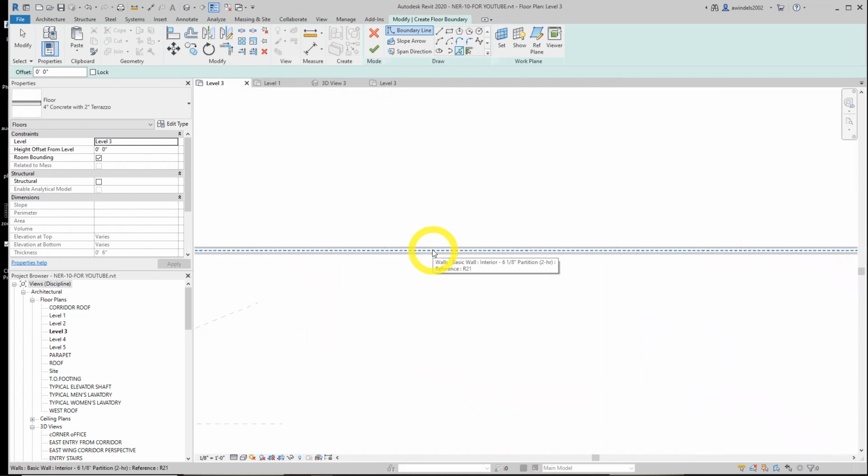Let's hover in here. And we pick the core of the wall, do 5 feet. Pick the core of the wall here. Make sure I get this right. This is maybe why my stairs weren't linking up right the first time I did this. This is core center line on this one. Okay, this one is to the core of this interior wall.